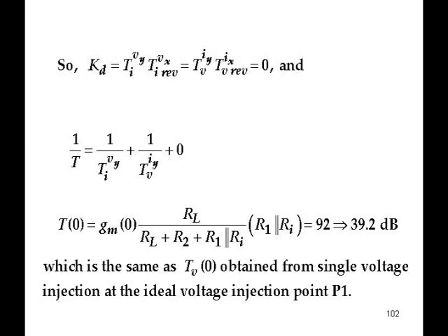So finally, you get to plug in the expression for T. The third term is zero, no reverse loop gains. And the T is the reciprocal sum of the current and voltage null loop gains. That's just like parallel combination of impedances, with the same consequence.